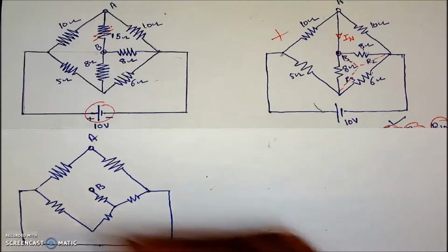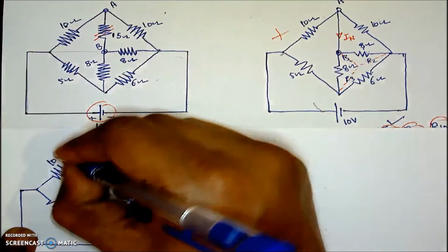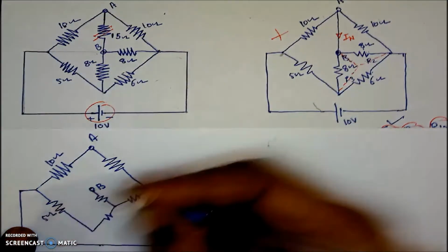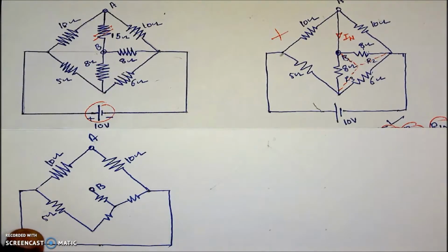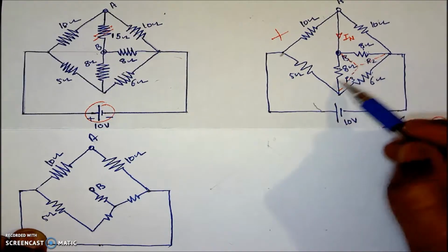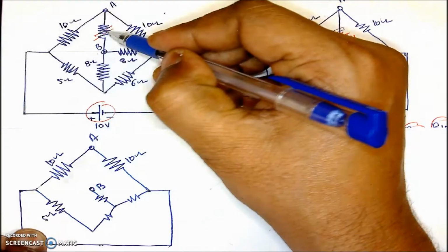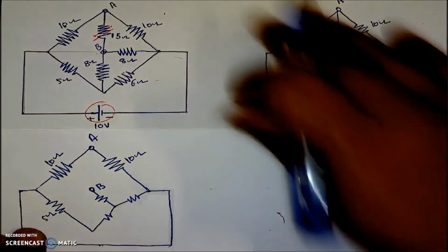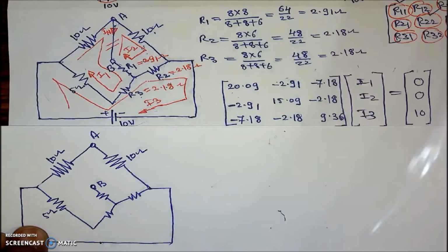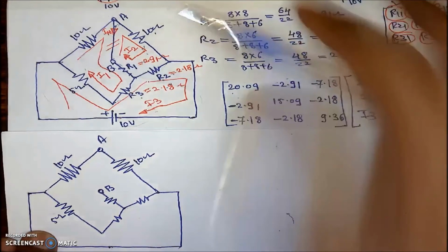Now look at this value, 10 ohm, I will take as it is. This 5 ohm as it is, this 10 ohm as it is. Then this delta is converted into the star; this short circuit should not be there because we are removing the load resistance. The calculations are available from the Norton's current calculation.